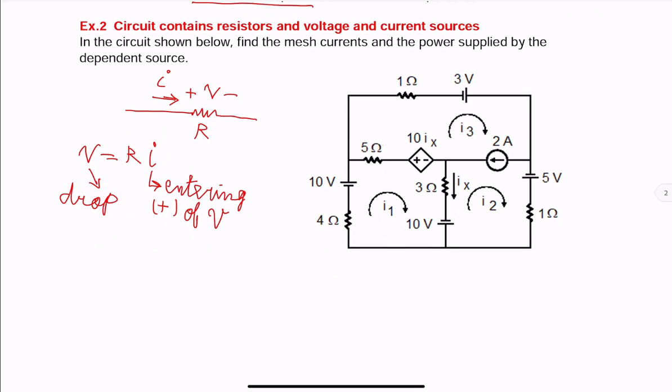So we look at the circuit, we have a current source. We cannot apply Kirchhoff's voltage law to mesh 2 or 3 simply because voltage across the current source is not known. So lots of books say combine mesh 2 and 3. We really do not combine those.